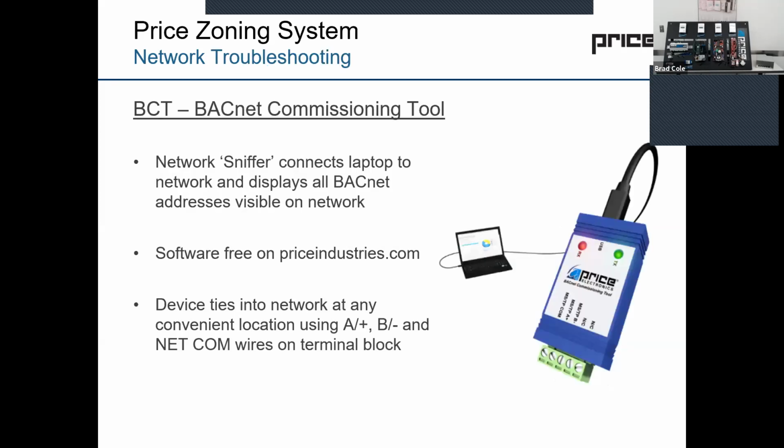And lastly, guys, we have this BACnet commissioning tool. So if you're on a site and the BACnet network's down and you can't get it in the ceiling and you don't have devices coming up and you're in a real tight spot, you can order this BCT from us. This has saved me on job sites, especially on finished sites, where you're sitting in a mechanical room, you're tied into the network, and you can see what devices are up and which ones are down. This thing is very useful if you run into some BACnet network issues where you can't solve them on your own, out in the network with what you have. This can help solve and save your BACnet network problems for sure.